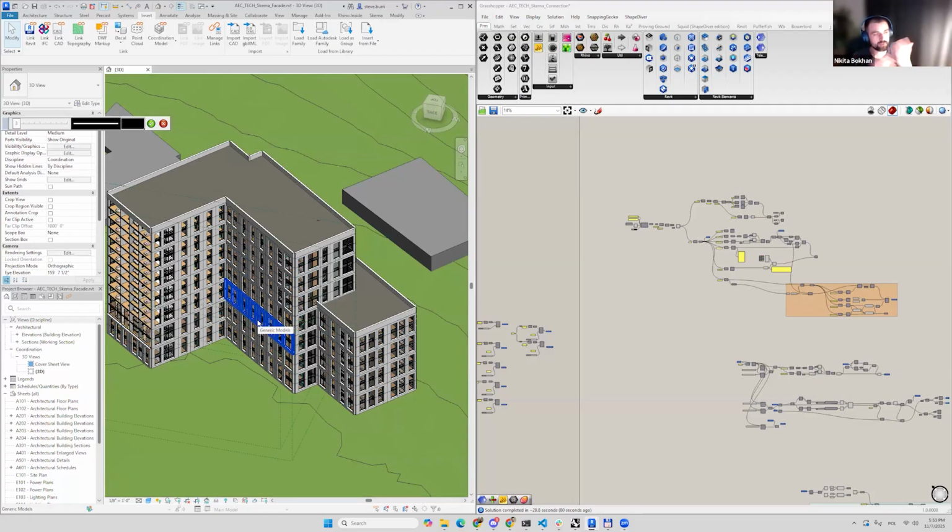So basically, for the exterior walls, we have three options for export: curtain walls, which is completely horrible, direct shapes, and generic walls. For this use case, we just select generic walls. It's just a proof of the entire workflow, where the schema is a mediator of the source, based on which we create the BIM model.